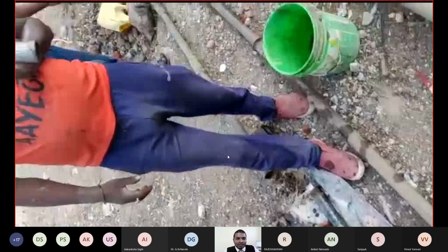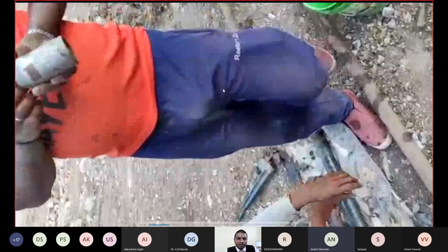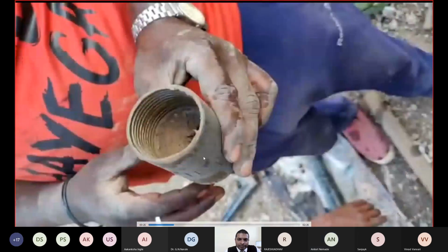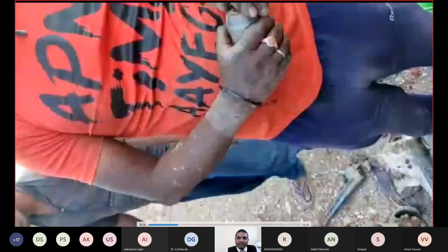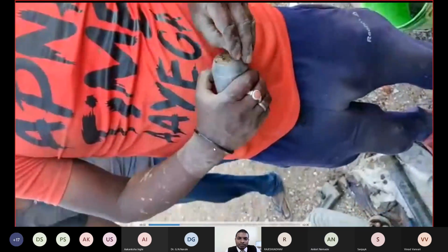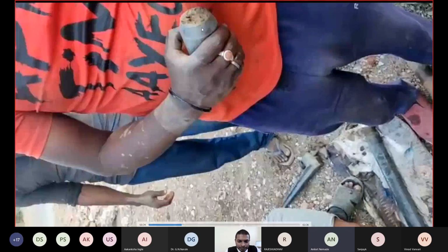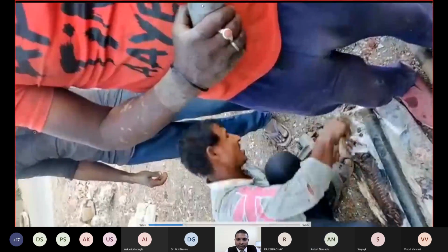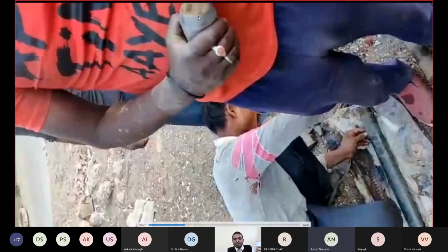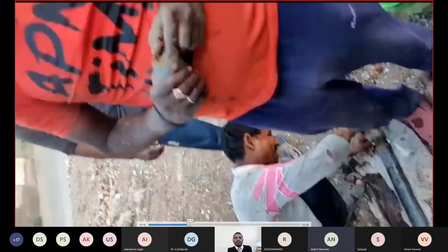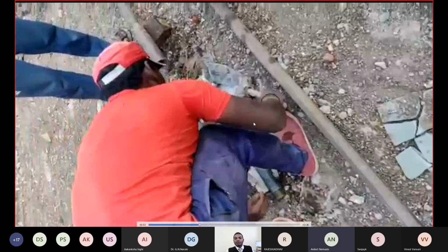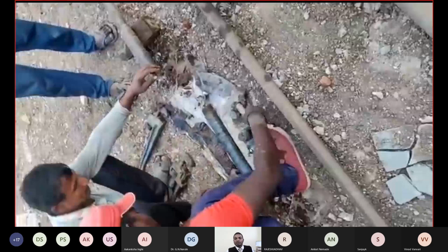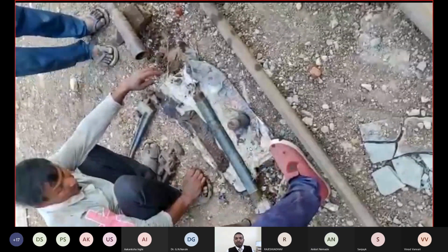Okay, it is showing the cone, its tip should be sufficiently sharp. So this is how things have been advanced, and your sample is collected in disturbed form, as you can see from the thickness of the blade. And now you can see that split spoon sampler actually. At this location, we found that there was a very clayey mixture, and thus it is taking too much time.